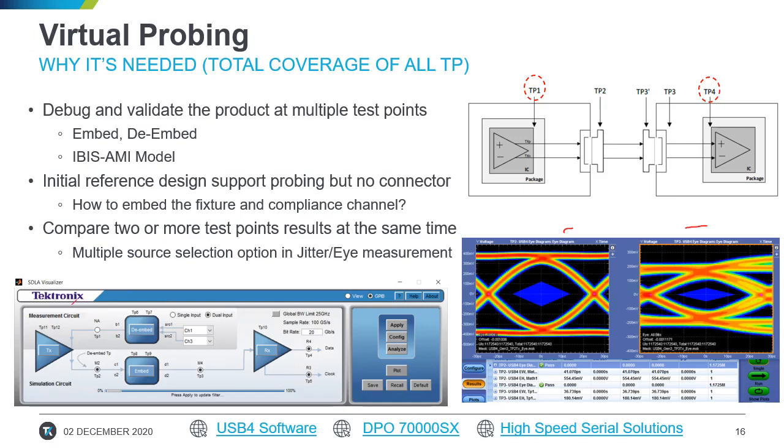If we don't have margin at TP2 itself, it will definitely fail at TP3. So we need to find the root cause. We can root cause the issues at TP2, not at TP3. So there is something wrong with the transmitter path, or something wrong happening in this path, that is causing the TP3 failure.